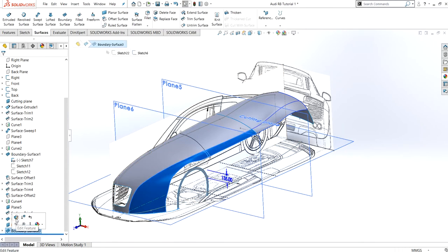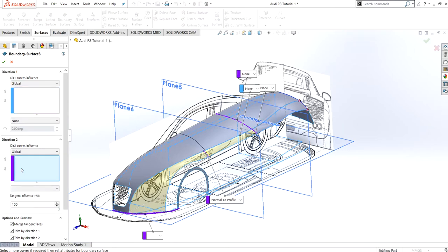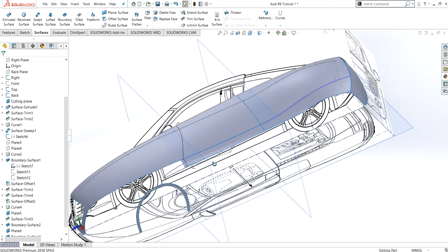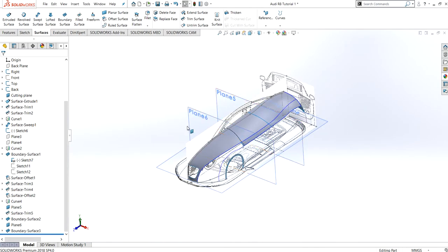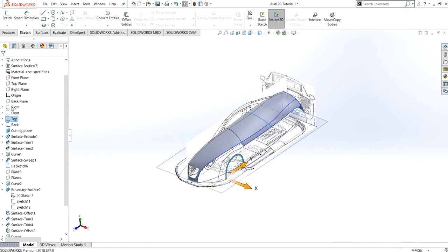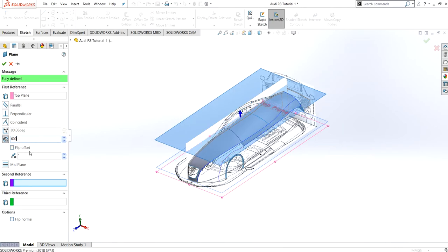It's changing. This one give tick. Now hide these two planes and click the top plane and drag it upwards to a height of 600 mm.